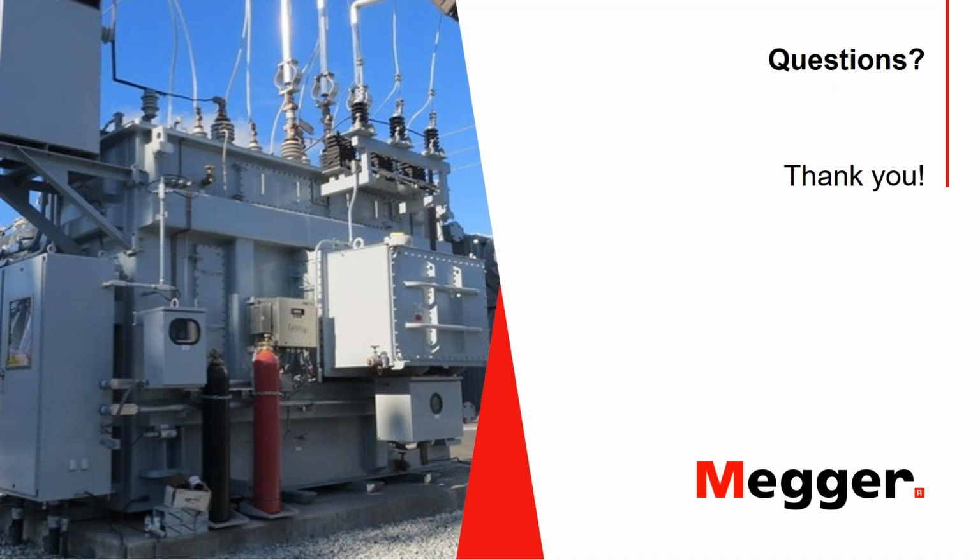It's a very interesting question because this comes up quite a number of times. When you talk about a de-energized tap changer, primarily in the US, you would find those on the high voltage side. Because voltage regulation typically takes place on the low voltage side, the DETC position could be set at one position for a long period of time. If the DETC tap has not been moved for a long time, it is recommended, and I believe it is even in the standard, that you not move the DETC contact during preventive maintenance, and you should only test the in-service tap of the DETC tap changer.